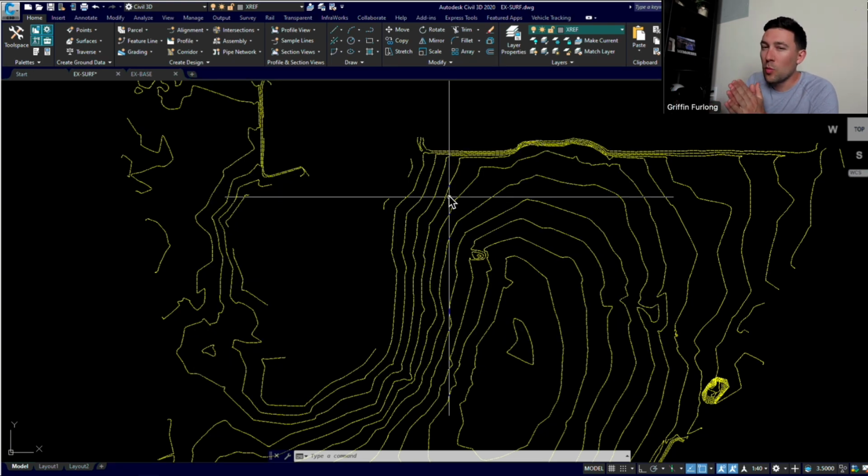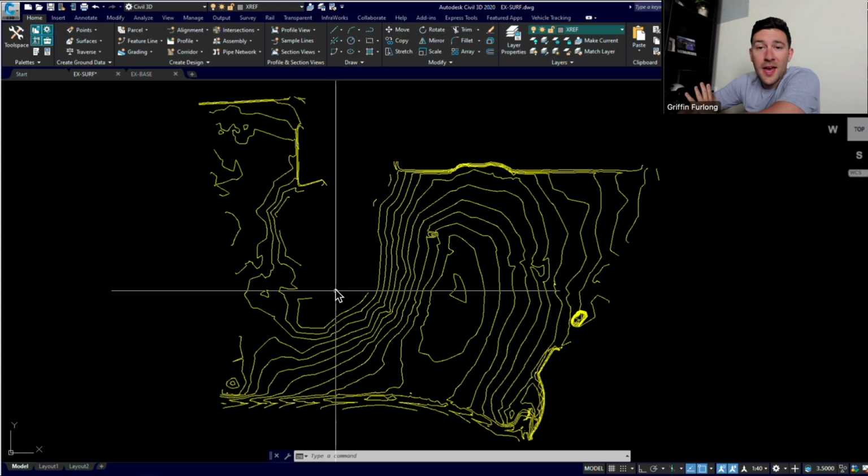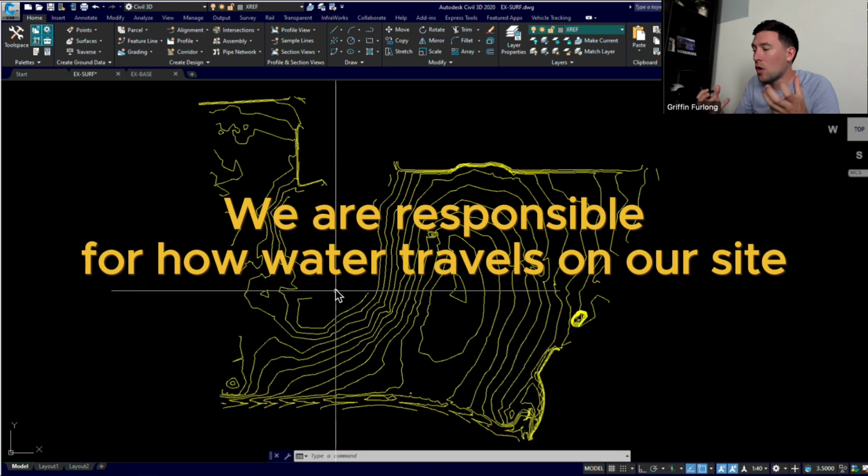Now, this will become way more important when we're developing our CN, or curve number, calculations, which won't be in this video. All right, with that, I think we're well on our way to really dive into this beast. I think it is very important to know your on-site versus your off-site basins. Think of it as we are responsible for controlling our own waters on our own lands that we own, and managing the basins of other lands that flow through our site.